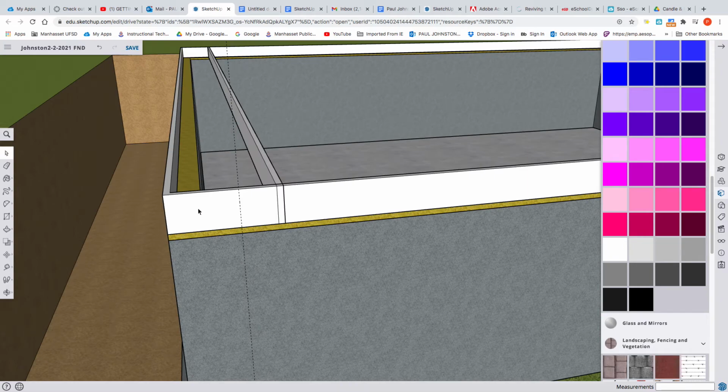Okay. Then I'm going to hit the space bar and select that tape line. I'm going to move a copy. So I'm going to tap M-Alt on this computer. If you're on a Chromebook, it would be M-Control. I'm going to drag it out here, and when I let go, sometimes it's good to go way out here so you can see it change.